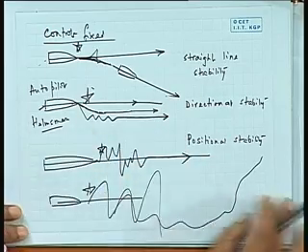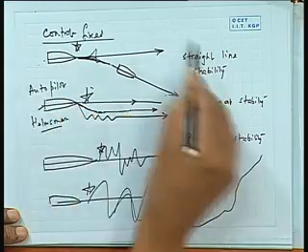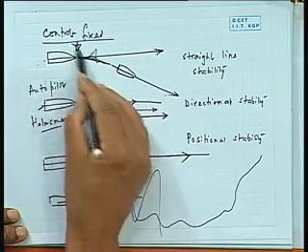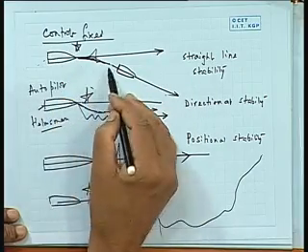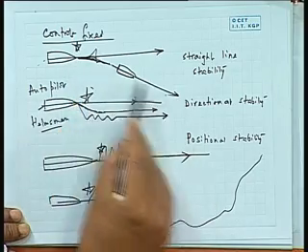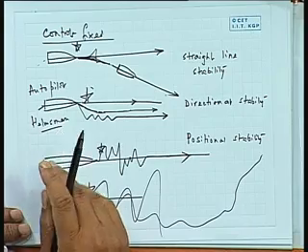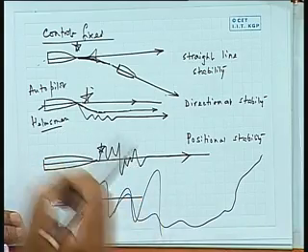Now normally what happens, initially we will be discussing the characteristic of the ship's inherent stability, because this part is connected to the hull. You want to know whether the hull has an intrinsic stability property, because if the hull is of this type, then it is much easier to control that with a rudder. See, if the ship tends to give a disturbance, tends to go this way, you can correct it by rudder, but you need much more rudder action. You have to continuously keep moving the rudder.